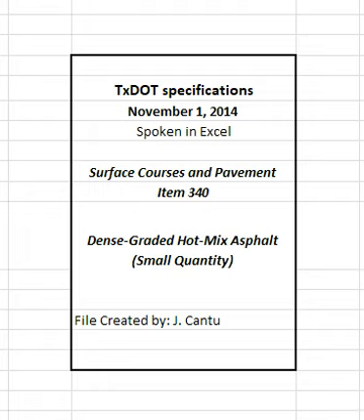2.6.2 Warm mix asphalt, WMA. Warm mix asphalt, WMA, is defined as HMA that is produced within a target temperature discharge range of 215 degrees Fahrenheit and 275 degrees Fahrenheit using approved WMA additives or processes from the department's MPL. WMA is allowed for use on all projects and is required when shown on the plans.